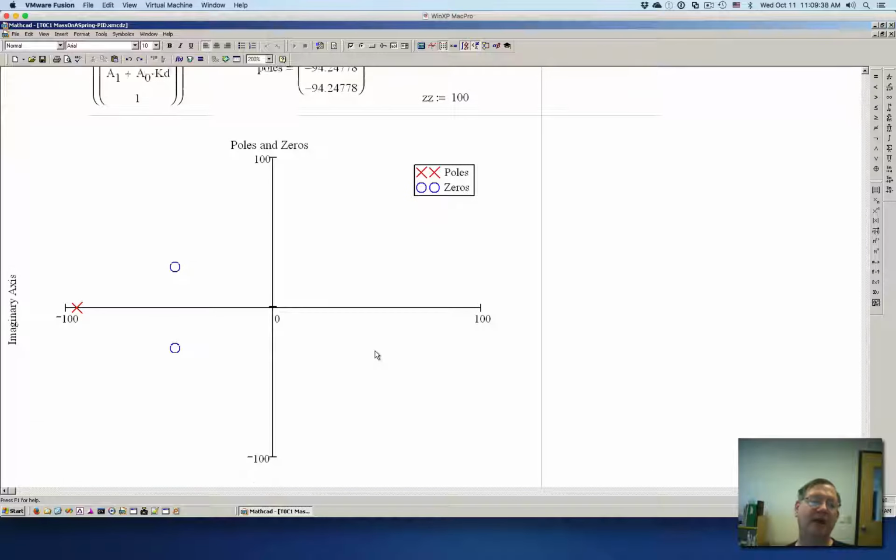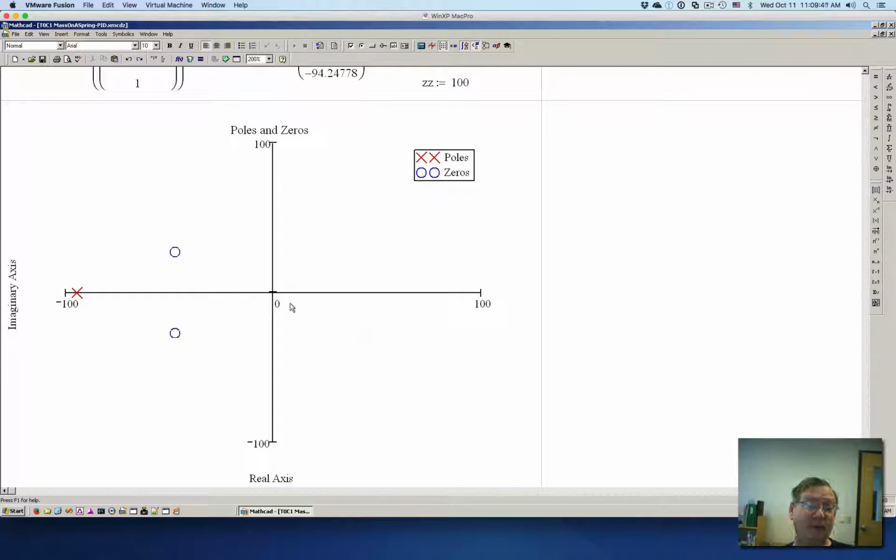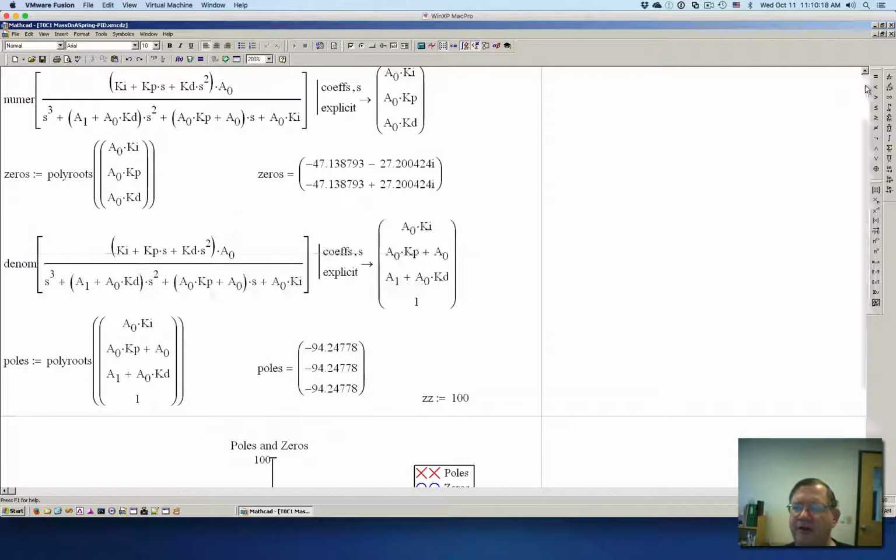Now, if you look at a pole zero plot, you can also tell this is going to overshoot, or potentially could overshoot, because if you start from the origin and start scanning to the left, you get to the zeros, which add phase lead and gain before you get to the poles, which then reduce the gain and introduce phase lag. And if we had enough energy at this point, we would get overshoot. But because the natural frequency of the system is 1/6 of a hertz, the energy kind of drops off right here, so these poles do not cause overshoot, as you've seen in the previous example.